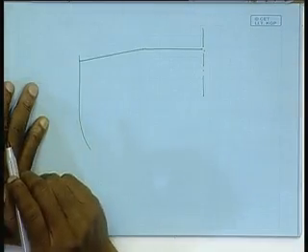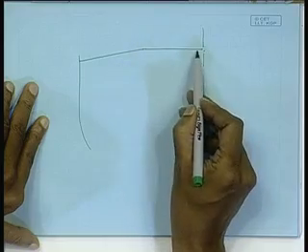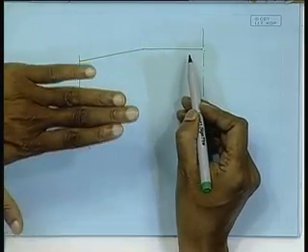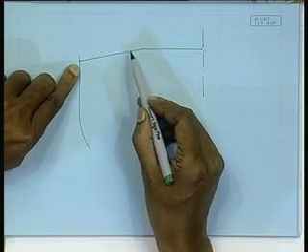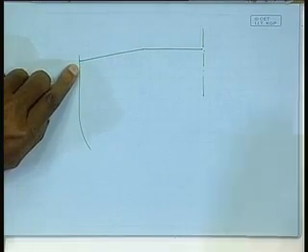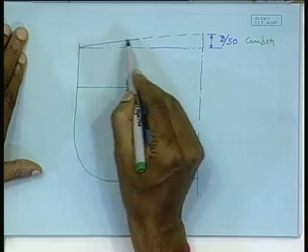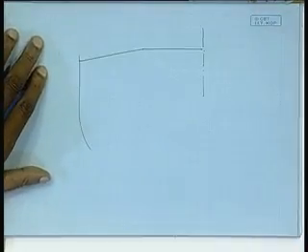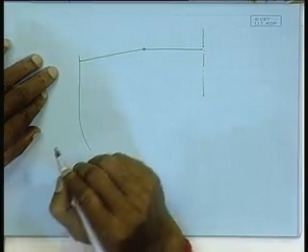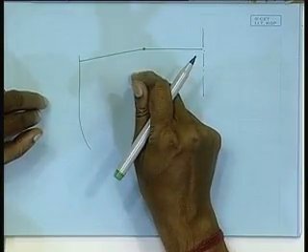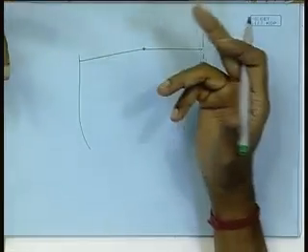Is it visible what I have done? The central part of the deck I have kept horizontal, flat. Only here I have made it again a flat plate, inclined. The difference between these two is it's a continuously curved plate, and here both are flat plates, welded here. Right. So, construction wise this is much easier. There is no bending operation involved. So, I can also do this. Now, depending on requirement, it can be done.